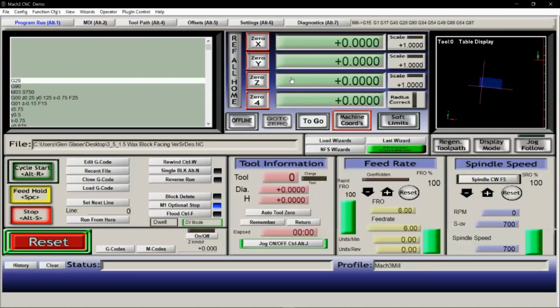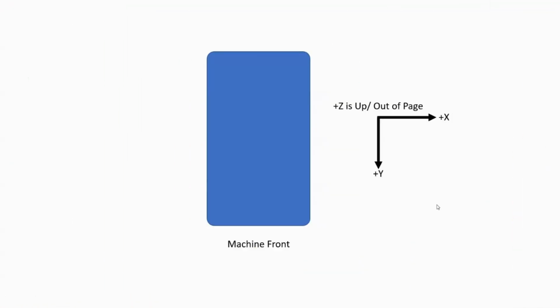There is the machine coordinates, which basically tells the machine this is where you are in space, and it works in tandem with the soft limits. Basically, the soft limits is an additional layer of safety. It acts like a digital limit switch. Once the machine coordinates get to a certain point and hit the soft limit, it will disengage the movement of that axis and warn you that you exceeded soft limits. To deactivate that, you just have to move the machine back into soft limits.